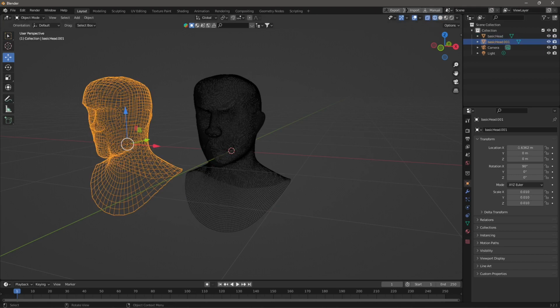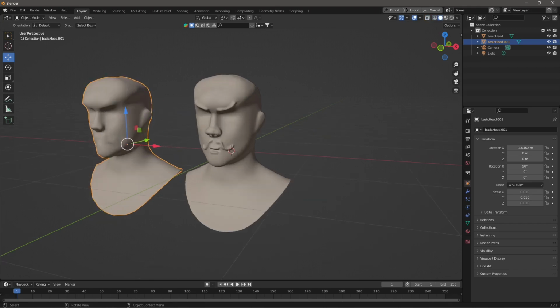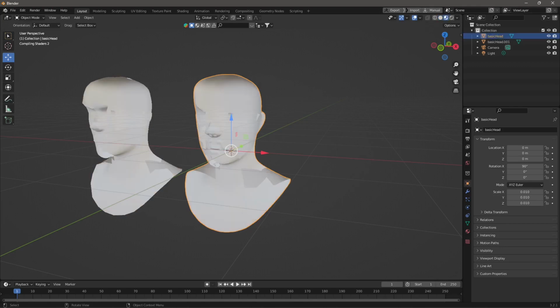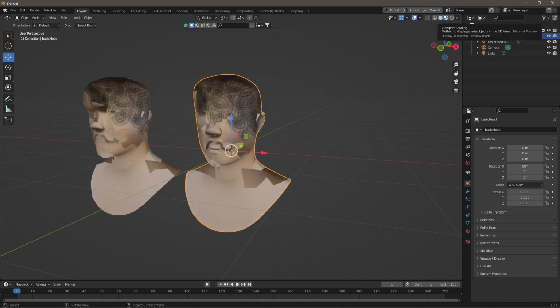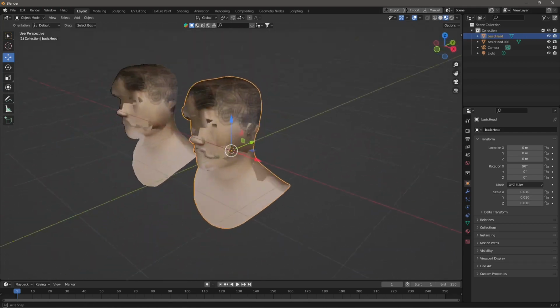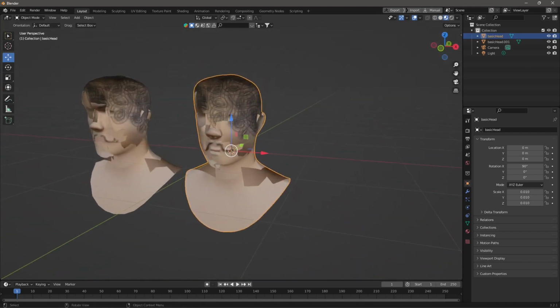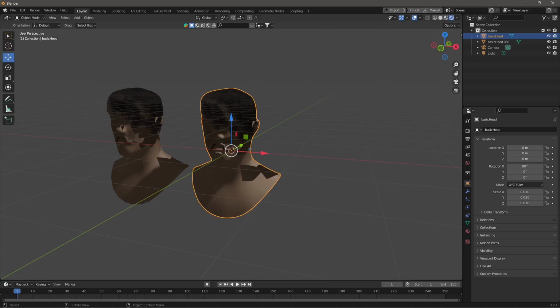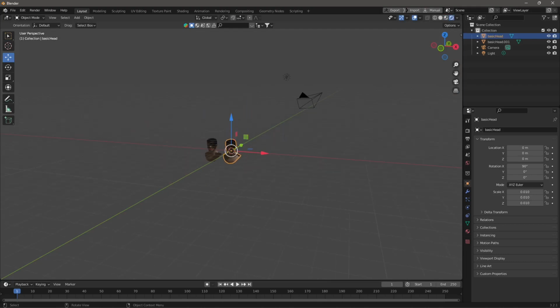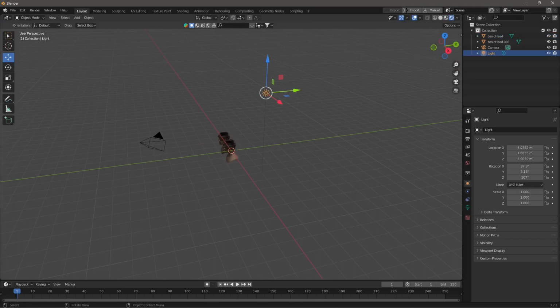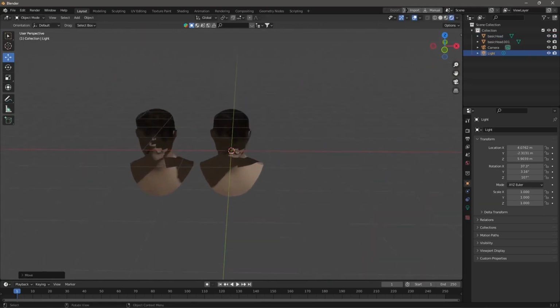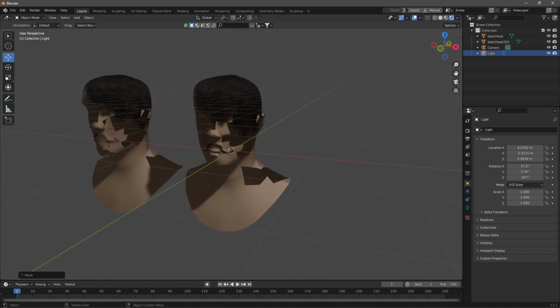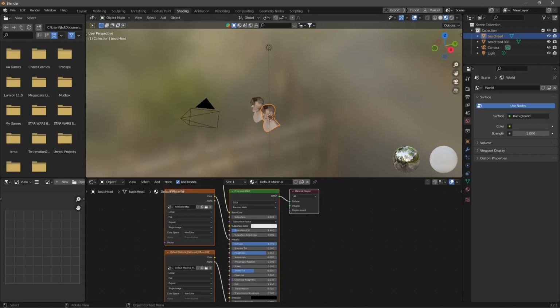So the more details you want to bring into Blender or another software, the more you need to increase the number of subdivisions. Now, if I move to the third sphere, we can see the texture, and we have also some issues with textures. So we need to fix that. And also, if I go to the fourth sphere on the top right corner, this is gonna show me the rendered version. So I can create a quick render using Cycles, and this is gonna show me the character now with the render, but it has some issues.